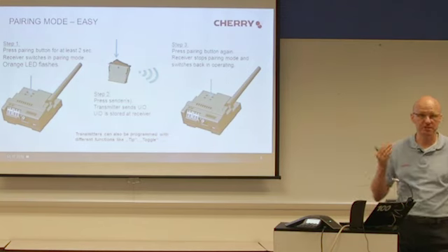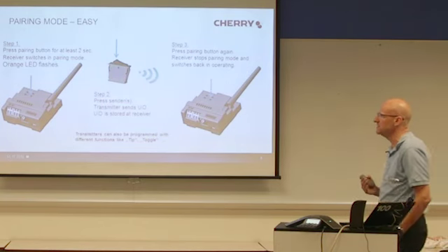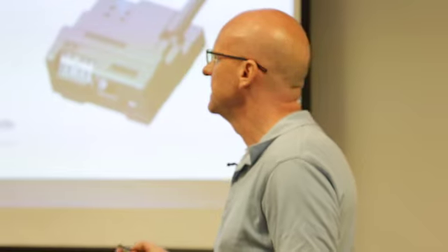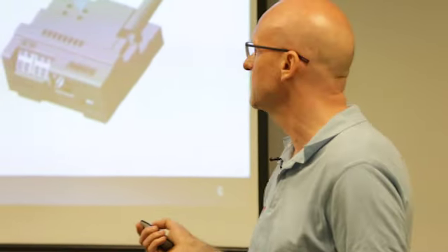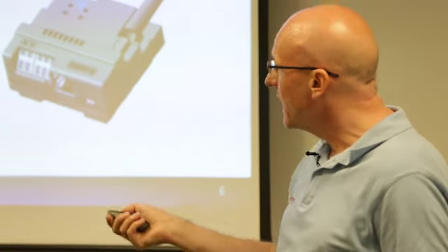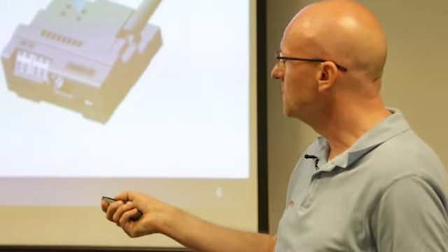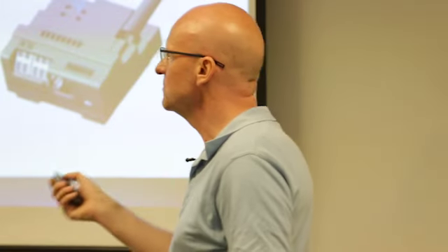The LED flashes and you can see, yes, the receiver is now in pairing mode. How it works and how the LED flashes is described very well in the receiver manual. When the receiver is in pairing mode, you press the switch you want to learn on the receiver. Or you press 2 switches or 3 switches, up to a maximum of 32 senders.